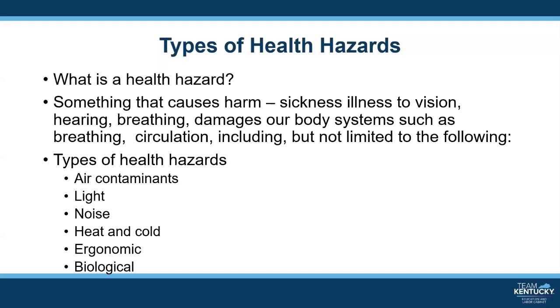Another health hazard is noise. Noise is created by the welder itself and the cutting and melting of the metals. Repeated and prolonged exposure to excessive noise could lead to hearing loss. We will discuss OSHA noise regulations in another webinar. Light is produced from the welding process. This light is ultraviolet light. It can cause damage to the cornea of the eyes and damage to the skin.